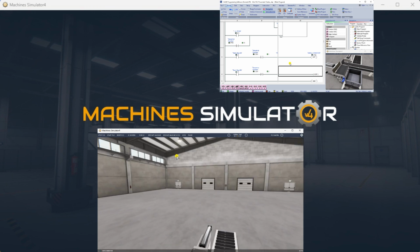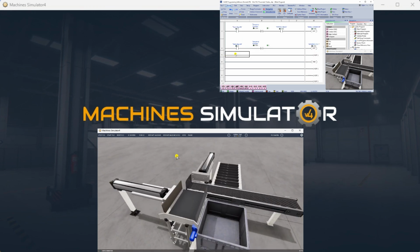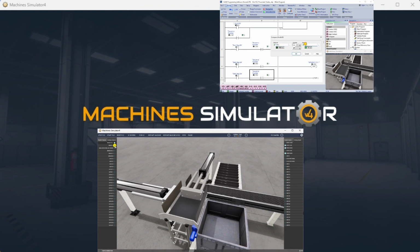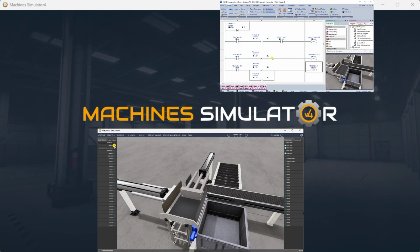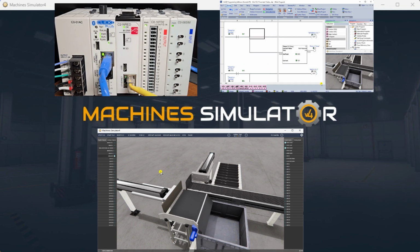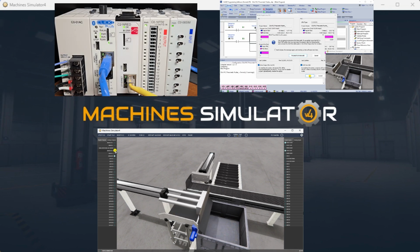We will use the Click PLC programming software to showcase a sequencer application for this example. In this scenario, 2 boxes on a conveyor belt are pushed onto a loading dock with a pneumatic pusher. When 8 boxes are accumulated on the dock loading, a second pneumatic pusher will move them into a crate.